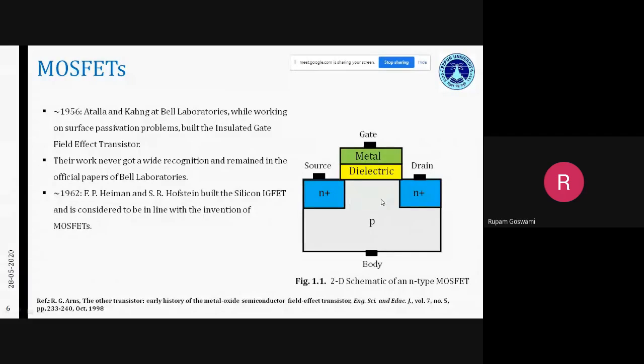So now when you are bringing this closer, the electric field emanating from the drain can now control some of the charges in your channel. So the gate is actually losing control. It is like you have a sweet shop in a particular area, and you are the owner of that shop. Now someone comes to you and says that I'll be taking this shop on lease for say 20 years. You don't usually have a problem if he takes only a very small share of your sweets or your profit.